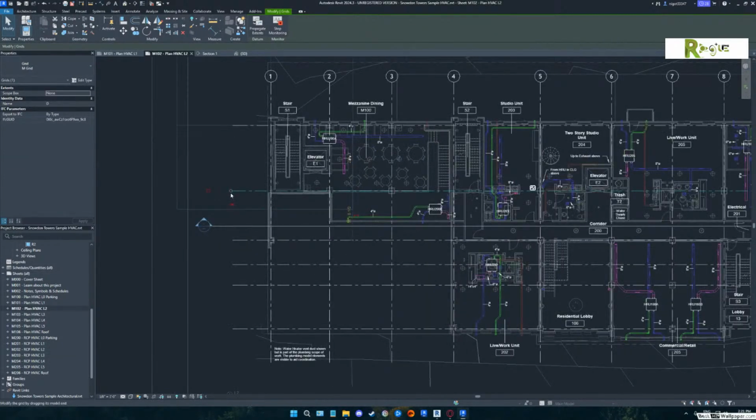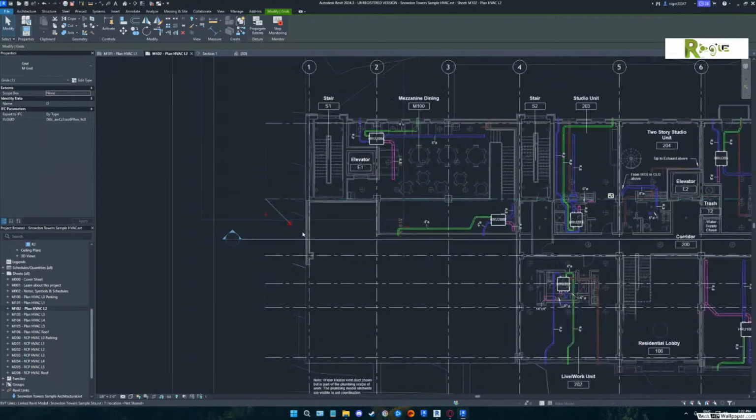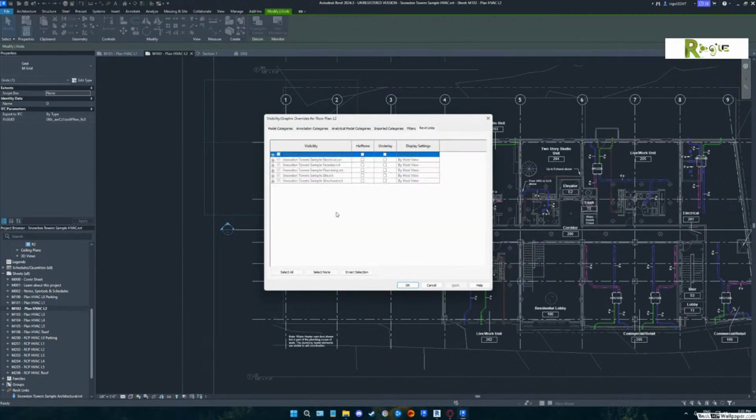So how did they turn the other grid lines off, Eric? From the other models, they didn't have the prefix of HVAC on the column grids, correct? No, we did that. Do a VV and show me the Revit links. See if they did that nonsense. You have to go to Revit links at the end, and they're set to match what the main model does. Looks like no, it's by host view.